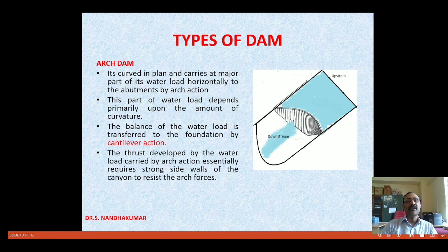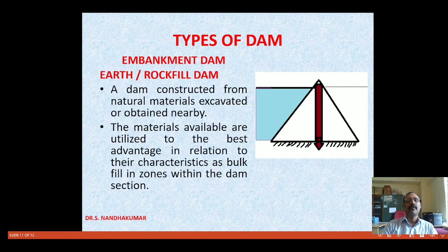The thrust developed by the water load is carried by the arch action, which essentially requires strong side walls of the canyon to resist the arch forces. So all the pressure is thoroughly dispersed through this design of the dam. That is arch action.